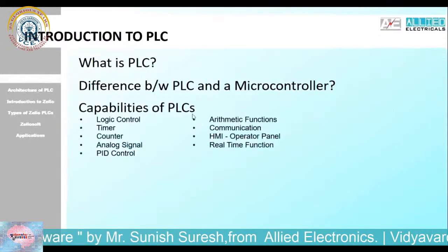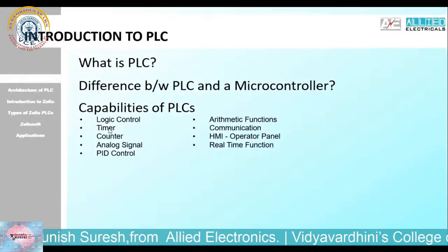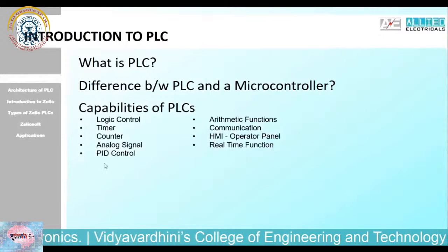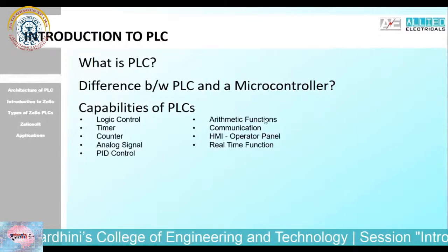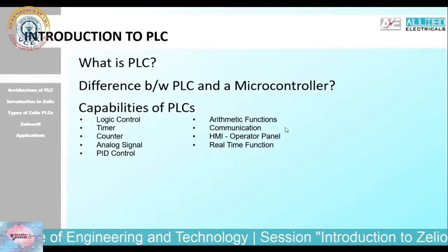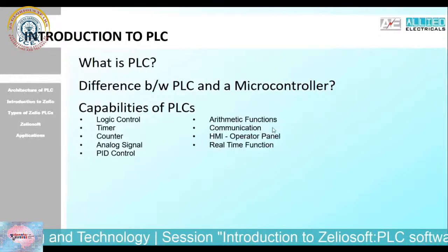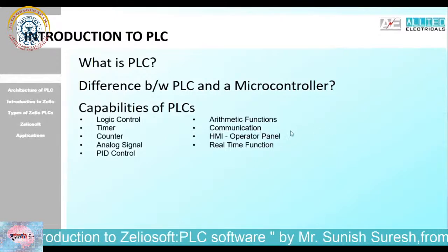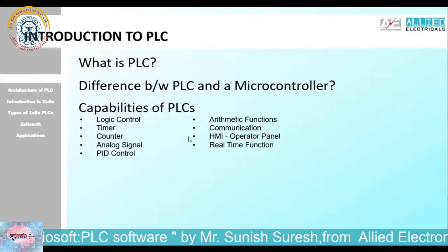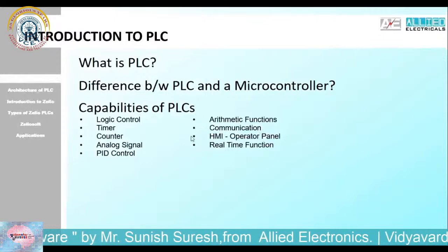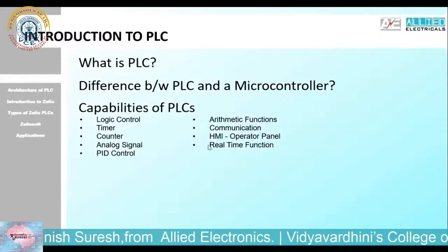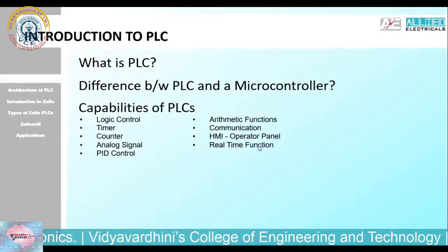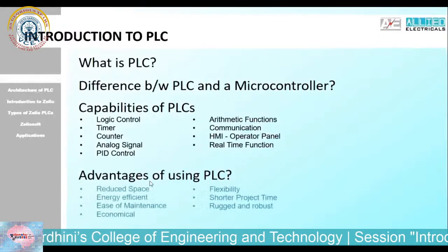Coming to the capabilities, PLCs are capable of performing various logical operations. They have timers, counters, can generate analog signals, and have PID control as well as arithmetic functions. The PLC also supports various communication protocols such as TCP/IP, Modbus, serial communication, OPC, etc. Also, the PLC can be connected to an HMI for better operational control. And the PLC also has a real-time function, that is the RTC.